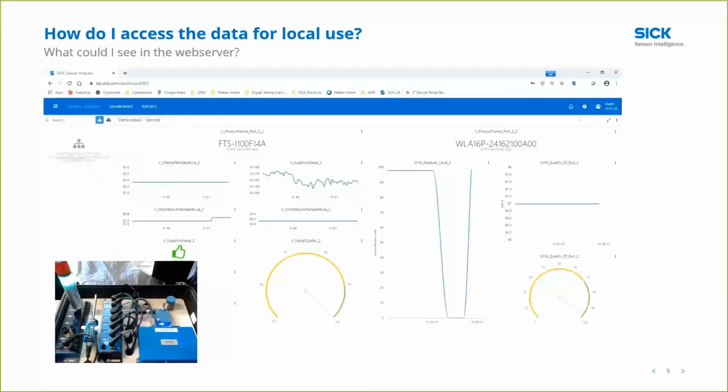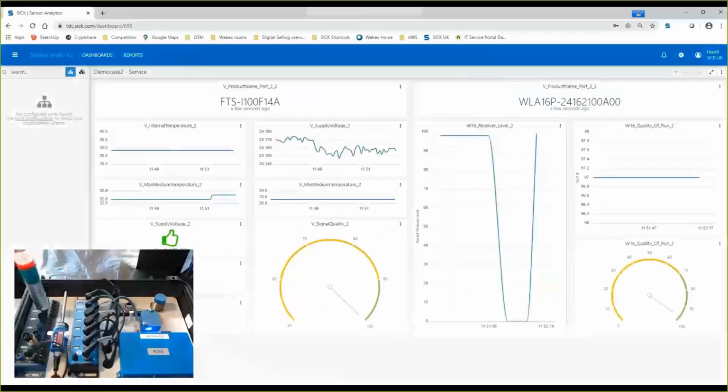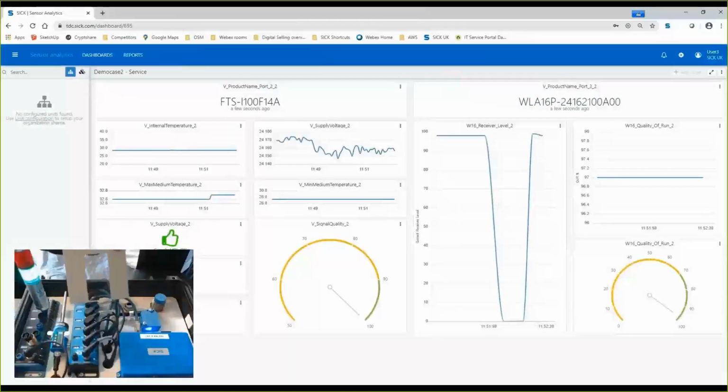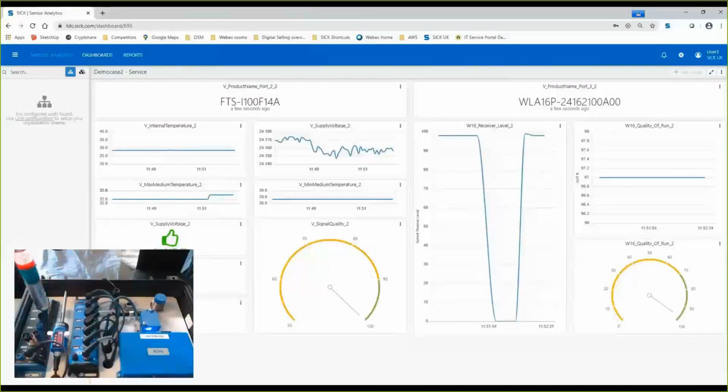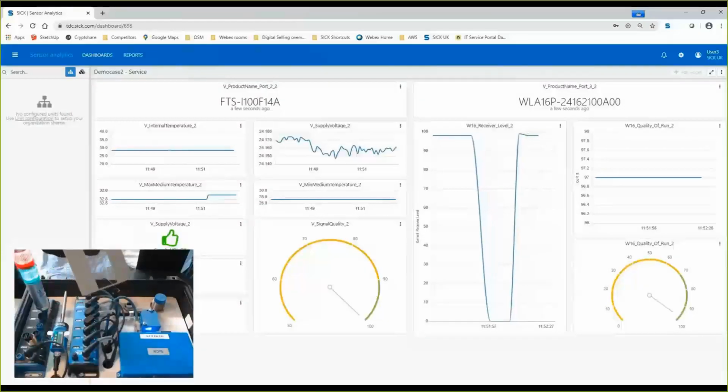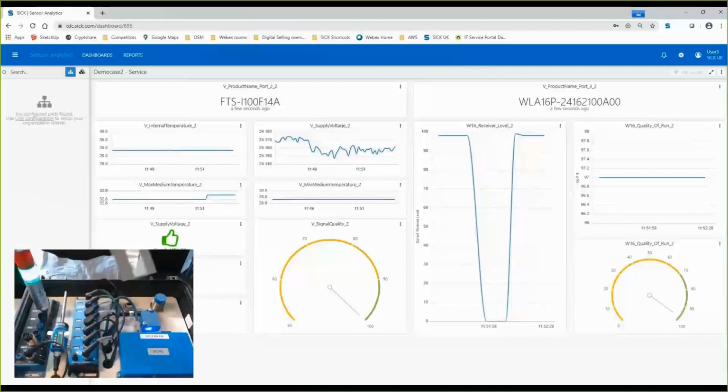Right, so we're going to be referring to contamination or dirt or signal quality, receiver level, those kinds of terms. To show that, if you just have a quick look here on this video, there's a little plastic window there. That plastic window is representing contamination. You'll see that when I pop it in front of the optical sensor, we will get a drop here.